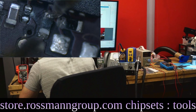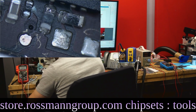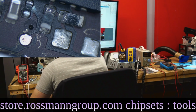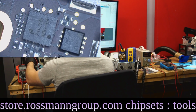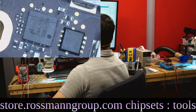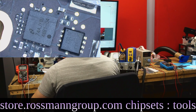So we measure the resistance, and it looks like we're getting 6.7 megaohms. That is probably not what this is supposed to be. It's probably dead. So the first thing that I would do in a situation like this is take a look at the top of the chip and see what it says. Because sometimes, on rare occasion, it'll actually be helpful, and it'll tell you the number of it so that you can Google it. So let's just show you what happens if we were to Google this and go from there.